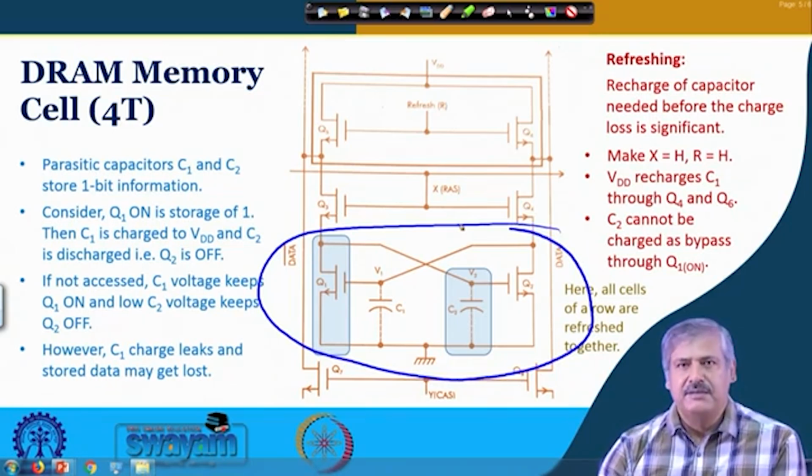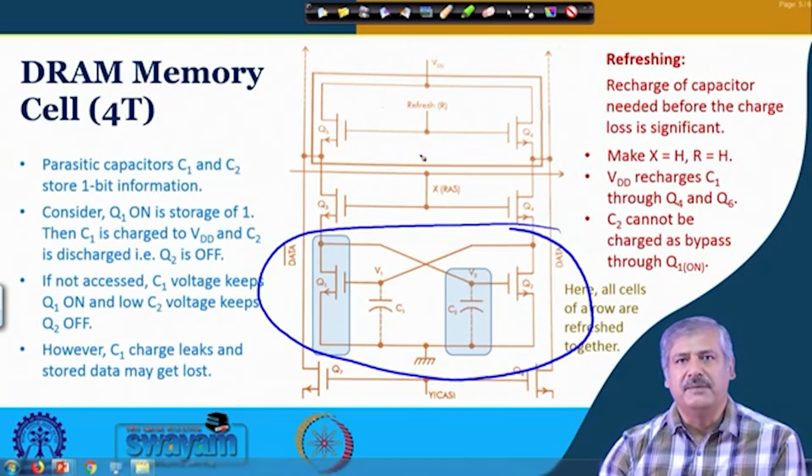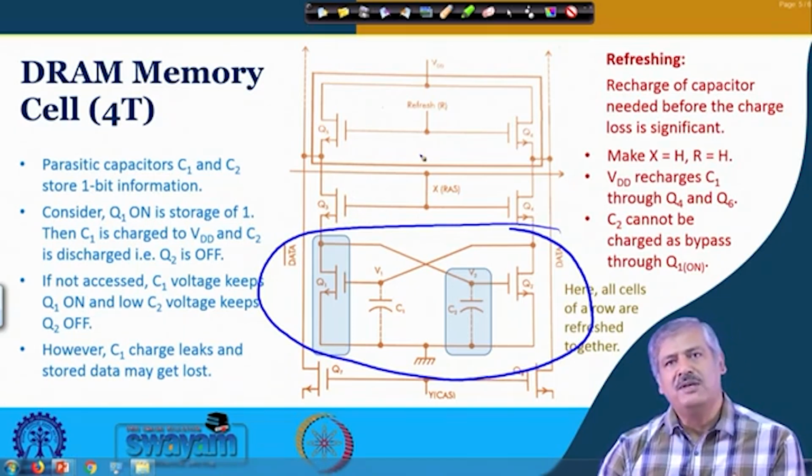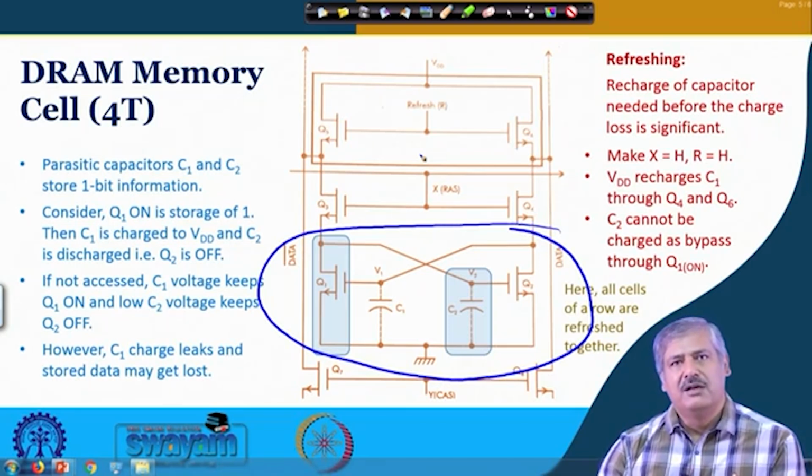In SRAM based memories using MOS, what we had after this was an NMOS load connected to VDD. This was always connected, and these opposite transistors were acting as inverters, and the memory cell was basically made up of these 6 transistors put together.